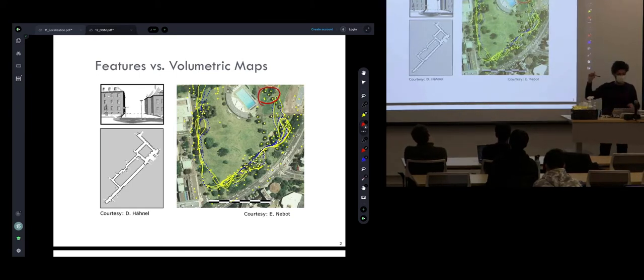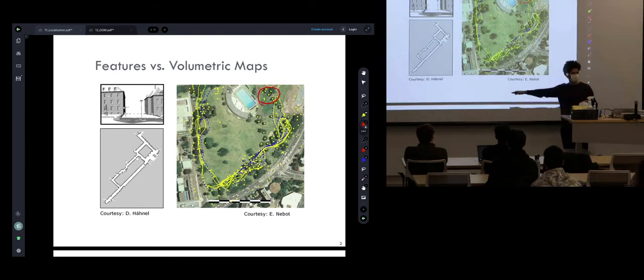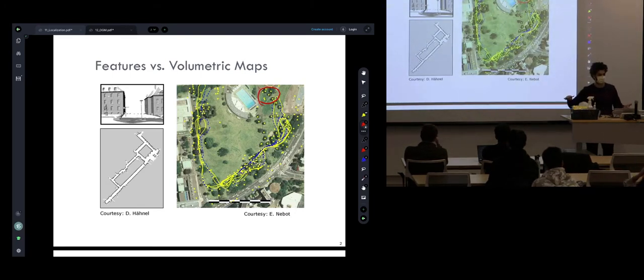So the landmarks, the points that you see, are obtained after processing raw sensor data from a laser rangefinder, a 2D point cloud, to detect the trunks of the trees in the park. So for the entire tree, when you detect the cross-section of it at the height of the vehicle, not very high, it will probably give you some line if you look at it from the front view, but you can consider that as a point. So there is a part that processes that data and will give you these 2D landmarks. It is open source. It's a piece of MATLAB code. It will process it for you.